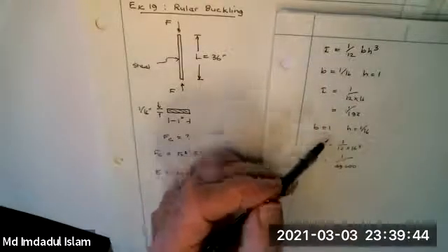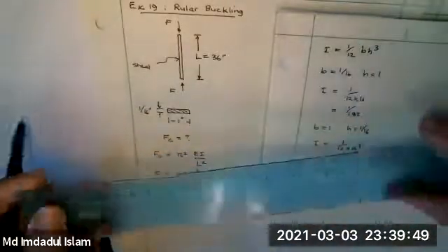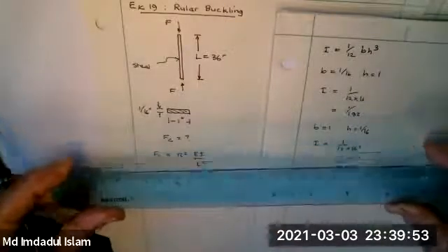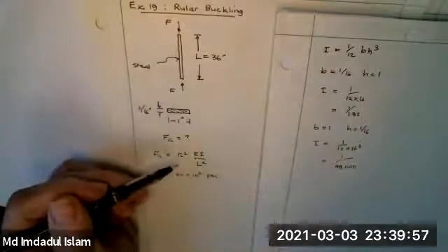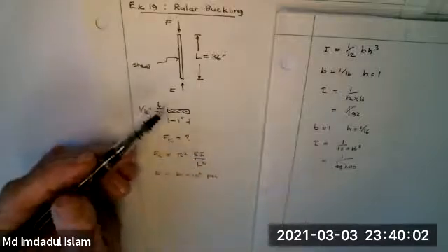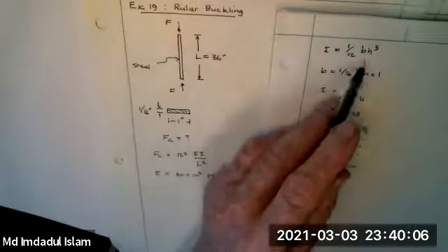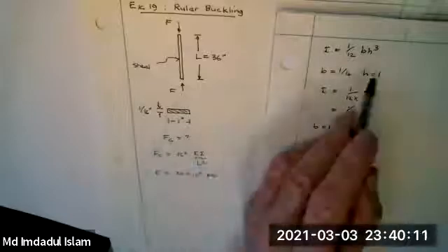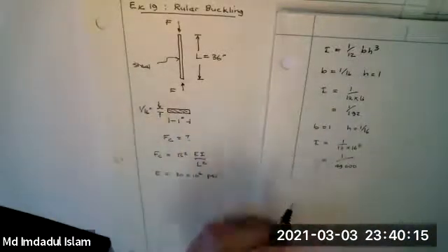It's like this thing here buckled that way. It didn't buckle this way. In fact, it won't buckle this way. So when you do these calculations, you pick the smallest I, because it's going to prefer that direction to buckle. It's going to choose the H which is smallest, and buckle transverse to H. So it's going to buckle in this direction.